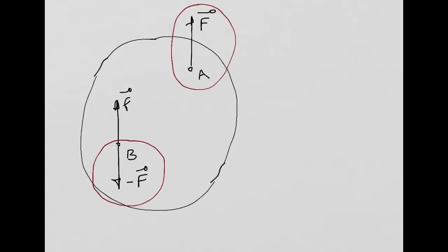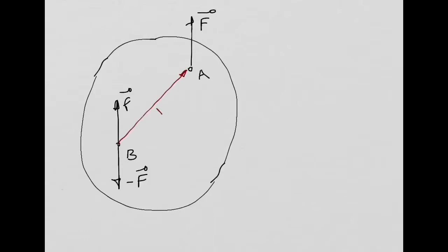In terms of forces. But a couple introduces a moment. And how much is that moment? That moment is equal to the cross product of the position vector connecting point B with point A. So the moment produced by that couple, I'm going to say M, is equal to the position vector r_BA cross product with my force vector.